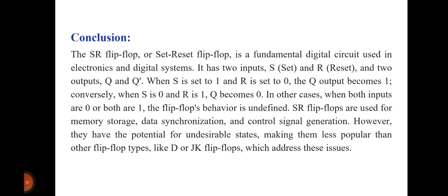When both inputs are 1, the flip-flop behavior is undefined. SR flip-flops are used for memory storage, data synchronization, and control signal generation. However, they have the potential for undesirable states, making them less popular than other flip-flop types like D or JK flip-flops, which address these issues.